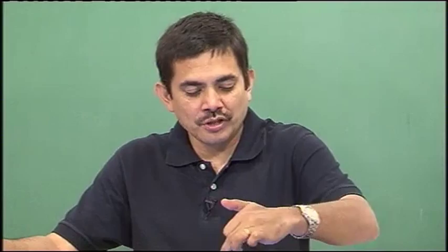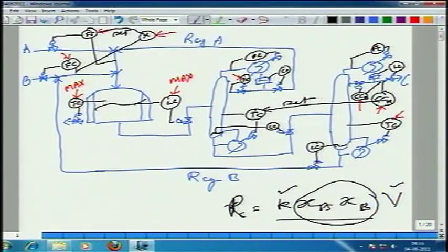If I put in more B, what happens? The ratio set point will ensure that I am also putting in more A. So, I am putting in more fresh A, more fresh B. So, the concentration of A and B inside the reactor actually goes up, yes or no? The concentrations of both will be equal to 1. No, no, no, there is also C in the reactor, because C is getting generated. So we are also adding to the volume.